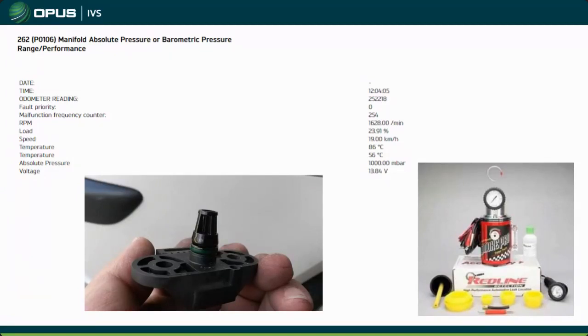And I will tell you that in my experience working here at Opus IVS and the calls that I get, more often than not, the aftermarket valves do not work correctly. The reason for that, especially on the 2 liters and 3 liters, but really especially on the 2 liter chain drive motors, is that there is that pressure regulation of the venting, right?